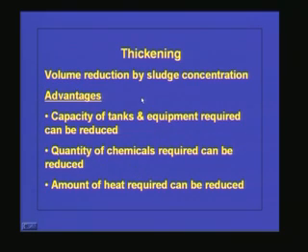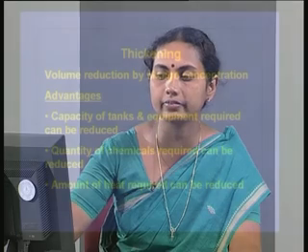Okay. Now we will talk about thickening. The preliminary process is over, and we know that the solids coming will have less than 5% of solids. If the solid concentration is less than 5%, we can imagine the remaining 95% is water. Because of this water content, the volume of the treatment unit we are going to provide will increase considerably, and definitely the treatment cost or capital cost will increase drastically. So if we can reduce the water content considerably, then definitely the volume of further treatment units will reduce significantly. That is the very purpose of thickening.